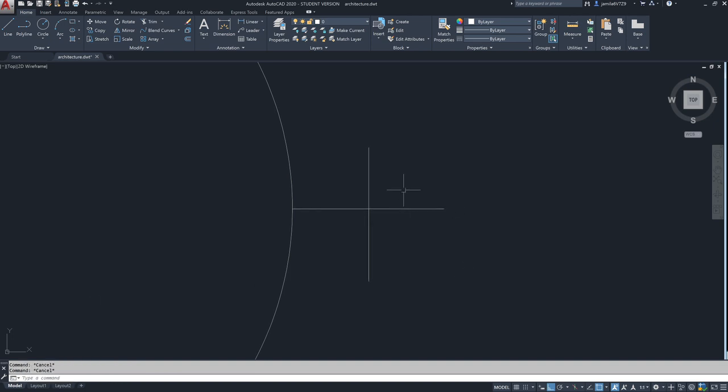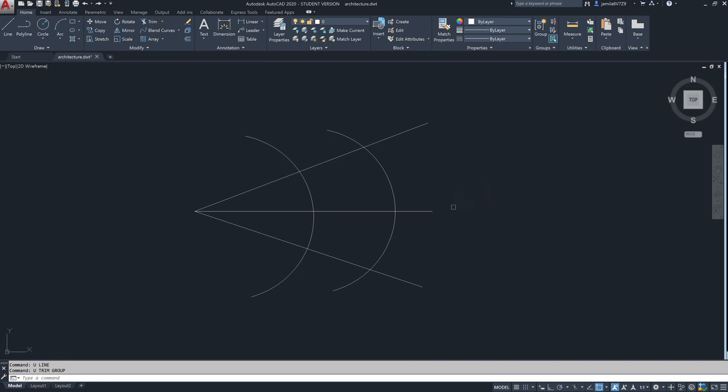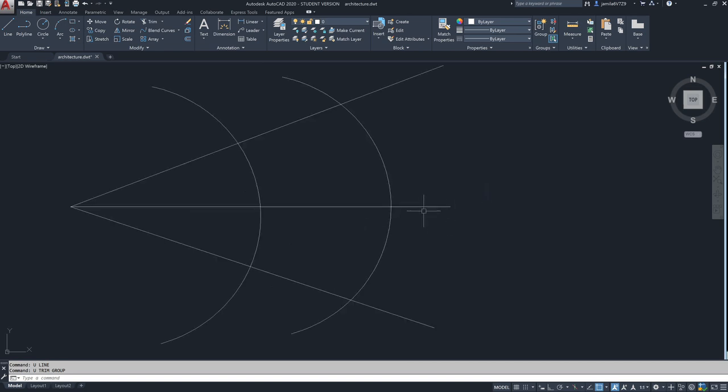Now, for example, I'm going to remove this line, actually undo quite a bit. Now let's just say I am going to remove this line all the way here. So I'm going to select the vertex and move that here. I just did that by stretching the vertex and moving that here. But what about the trim command? How do we do that? Well, you can do that by selecting a reference object. I'm going to undo, and I'm going to use TR.